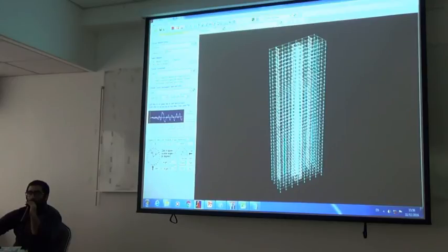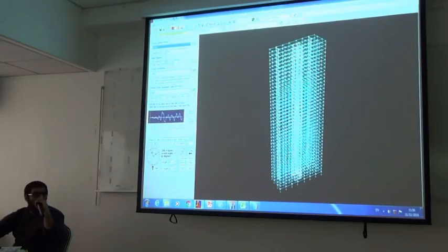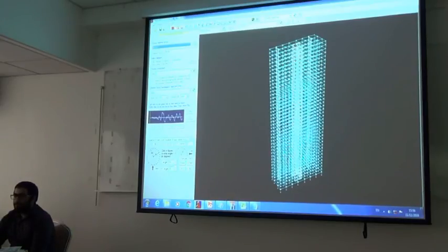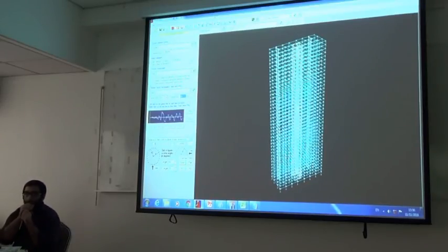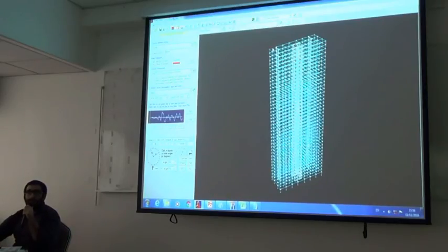After you select the hysteretic loops, you can select the group type as girders, right? So I'll wait for you to select this one first. Okay, so after this tab is already open, you can select a single girder, right? After you select the girder, you can see that you have different types of components in that girder. You have hinges, you have elastic component, but the hysteretic behavior will be shown in the hinge. So you just drop down and then select the hinge, and then you ask the program to plot, right?